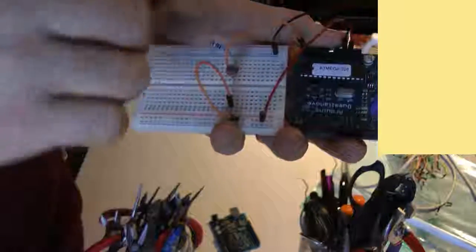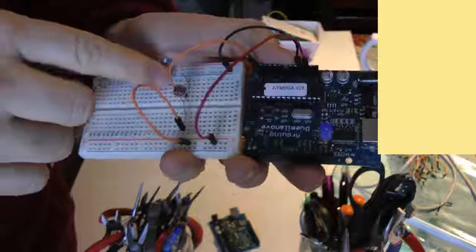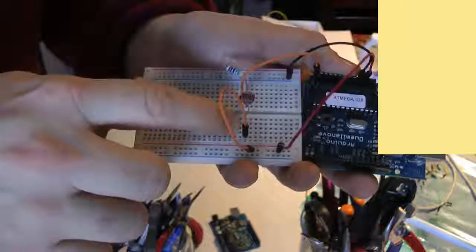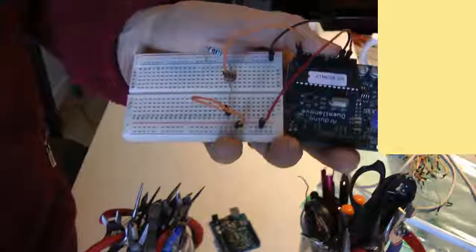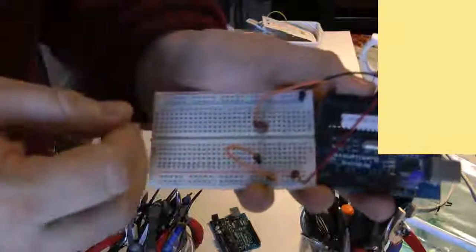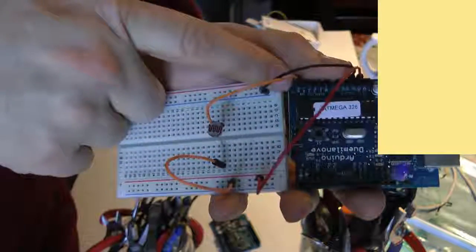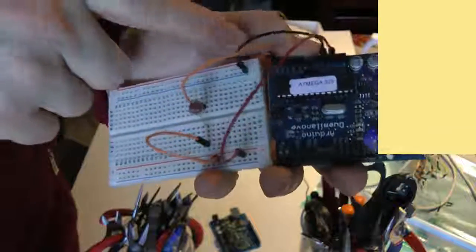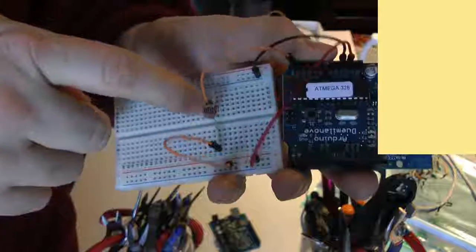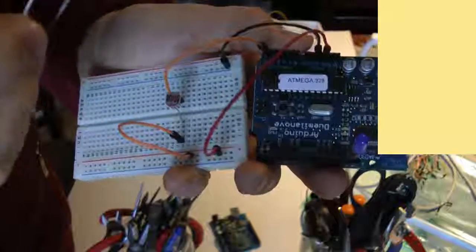We also brought ground over to the Arduino. And then we brought the 5-volt positive over to one side of the LDR. It doesn't make a difference which side because there's no polarity. And then the other side of the LDR goes into our analog sensor pin right there. But when we did that, it stayed at 1023, the highest voltage, because there was nowhere for it to go. It doesn't drain through that pin, so we've got to give it a place to drain through.